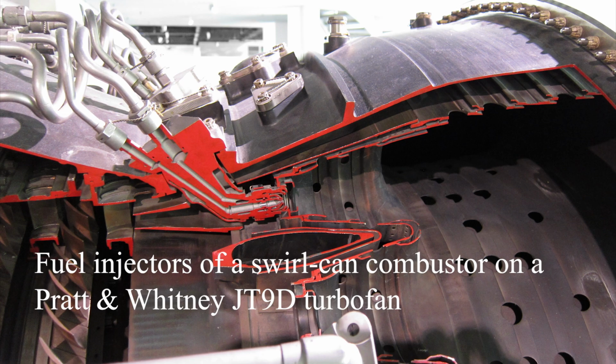This type of fuel injector has the advantage of being very simple, but it has several disadvantages. The fuel system must be robust enough to withstand such high pressures, and the fuel tends to be heterogeneously atomized, resulting in incomplete or uneven combustion, which has more pollutants and smoke. The second type of fuel injector is the air blast injector.